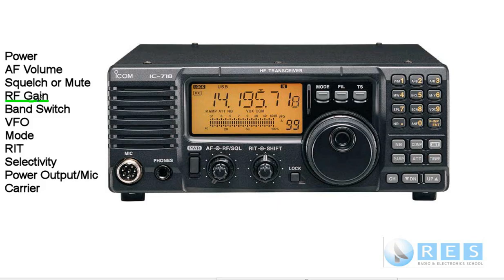If you're receiving strong signals, you don't want the RF gain up very high. If you're receiving weak signals, you want it up very high. If you're checking to see if a frequency is in use, you should turn the RF gain up very high to make sure the receiver in your transceiver is set to maximum sensitivity.